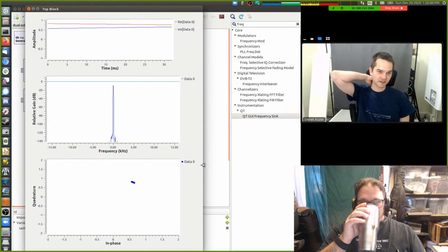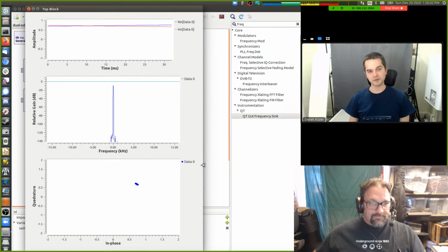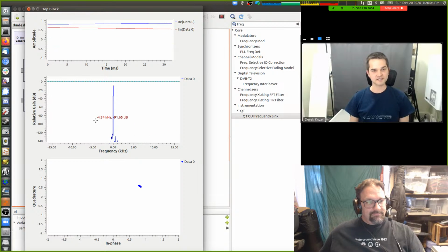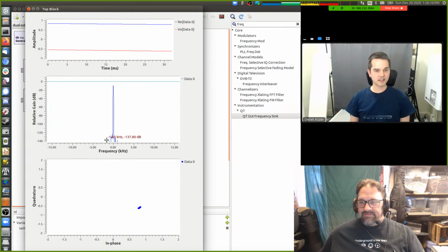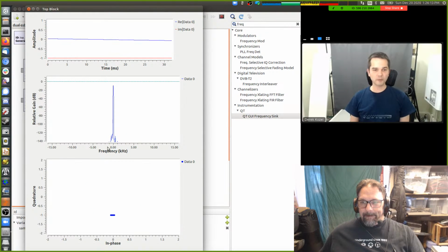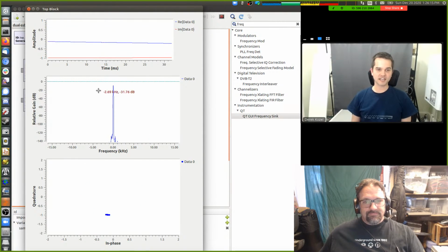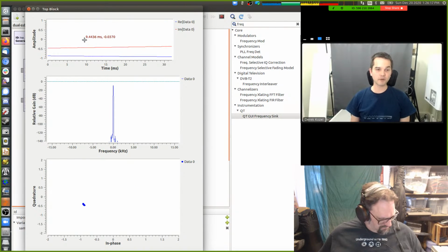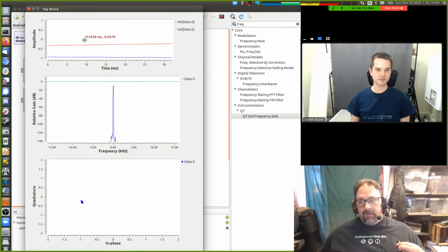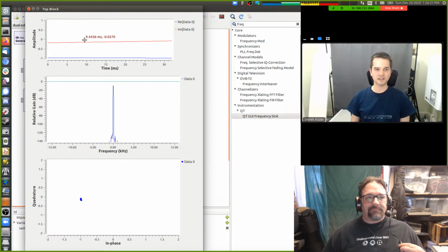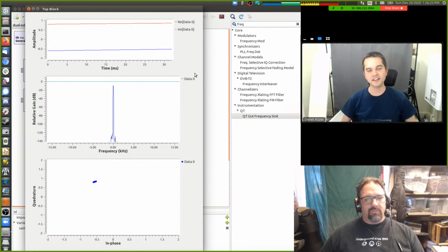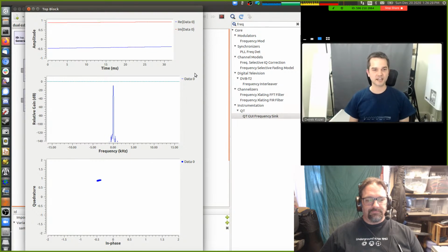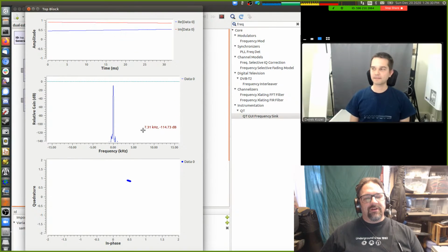first of all, our frequency sink is not actually going to be hugely useful, but let's kind of ignore all the noise down there you were talking about. That's like the aliasing, and it was well pointed out to me that quite a lot of that will be the numerical noise that I was talking about, and the other bits of it will be the FFT window, or the Fourier transform window that's applied. You get side lobes when they don't actually exist.